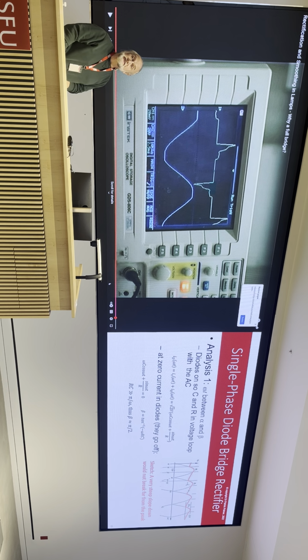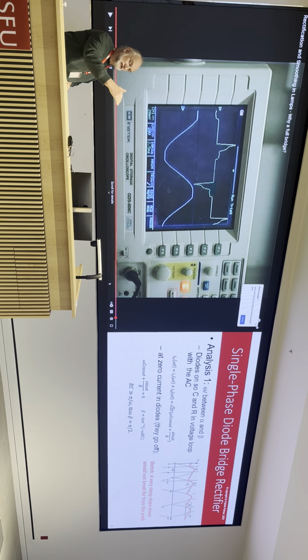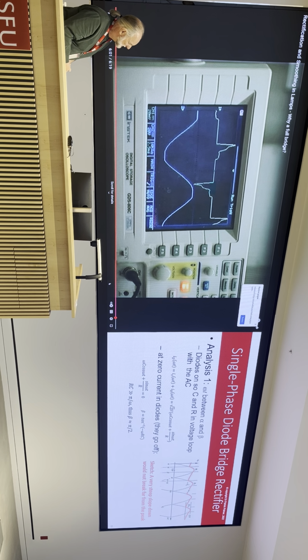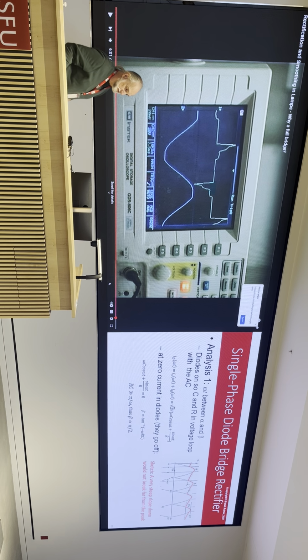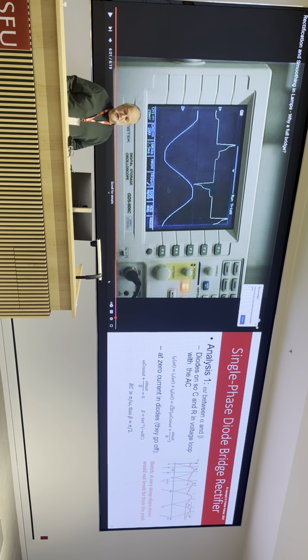So it's not the LED lighting that's doing that, it's probably the three-phase rectifiers that are around the system. But that's pulling current, these bits of current. There might be other things as well, but it's pulling bits of current out of the supply and flattening down the top, which is pretty unpleasant actually, not good for the supply. And this does cause problems. SFU Burnaby sometimes has problems, YVR has problems sometimes with harmonics from all these rectified loads and what have you. So there we go.